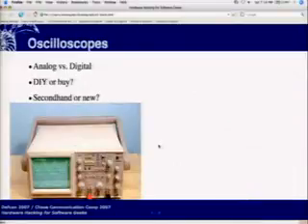Another useful use for an analog oscilloscope is when you're debugging your PCB layouts and you're looking for EMI, which might be affecting the operation. So you don't know why it doesn't work, and you've double checked your logic 15 times. You might find that interference from, say, the power supply part of the board is coming in on your analog inputs, and it's not properly isolated with the grounding, and the components are too close, and you might get some signal leakage even though the traces are isolated, but they're just too close on the board. So that will show you exactly what is on that wire, and what is on all the other spots, without having to guess.